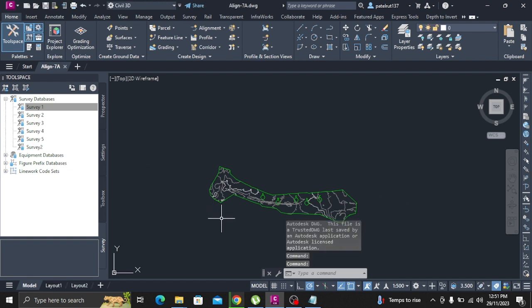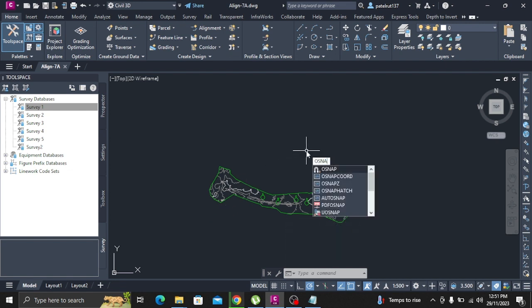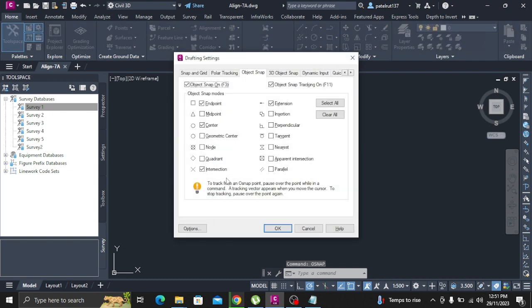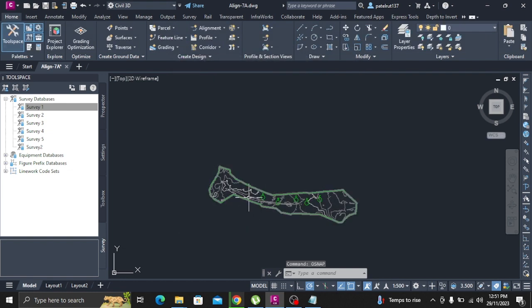In the Create Alignment Layout dialog box, accept the default values for name and starting station. Leave the description field blank for this exercise. On the General tab, specify the following parameters. Site: none. Alignment style: design style. Alignment layer: C-Road. Alignment label set: major, minor and geometry points.